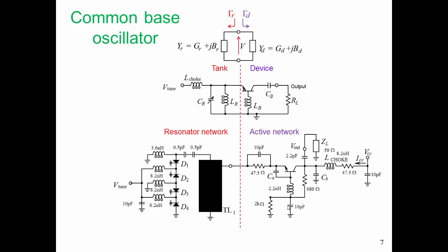The circuit that we're going to design is shown on the bottom of the slide here, and these 3 circuits show the evolution. The first stage, we want to design a reflection oscillator. A classic topology to implement a reflection oscillator is a modified Colpitts common base oscillator shown there.